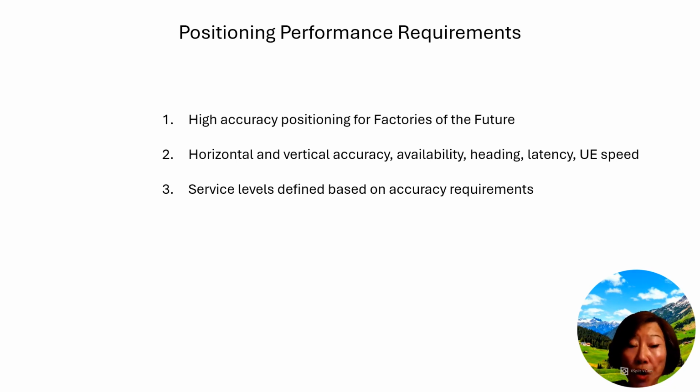One key feature is the use of beamforming and massive MIMO technology, which allows for very precise angle of arrival measurements. This is complemented by time difference of arrival, TDOA in short, measurements, using the synchronization signals in 5G New Radio. For even higher accuracy, 5G supports carrier phase measurements similar to those used in RTK GPS, which can provide centimeter level accuracy under ideal conditions.